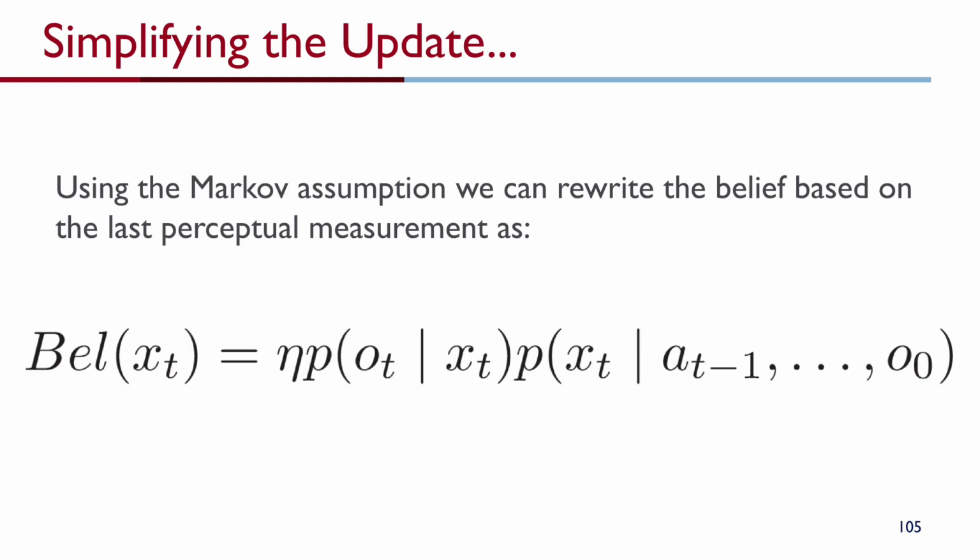It estimates the posterior distribution over robot poses conditioned on sensor data. In general, a Bayes filter solves the problem of estimating the state of a dynamical system. In our case, a mobile robot moving in its environment. The robot's state usually includes its position in the XY plane and its heading direction. Its measurements may come from range sensors like LiDAR, from cameras, or from odometry. Bayes filters rely on the Markov assumption. Past and future data are independent once we know the current state. We will make this assumption explicit in the next slides.